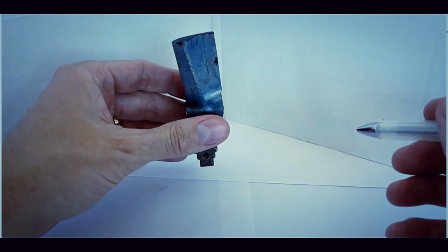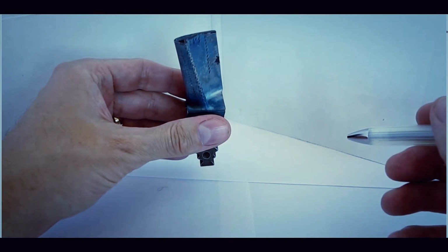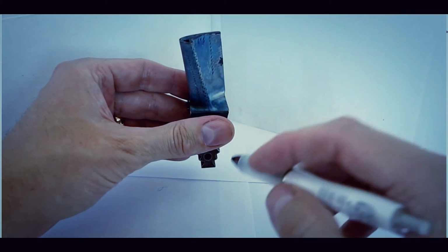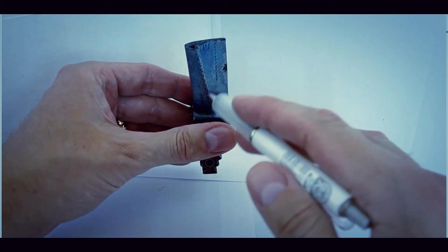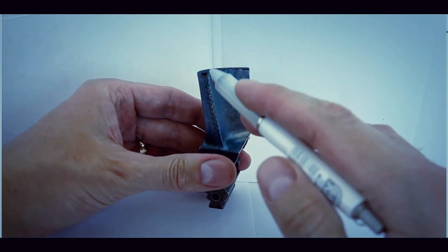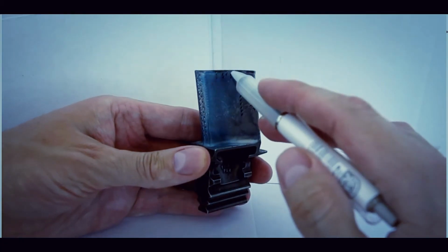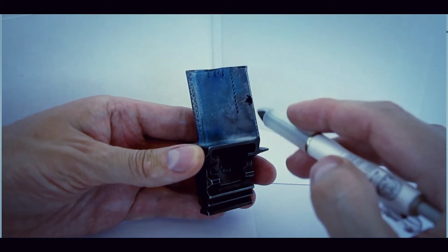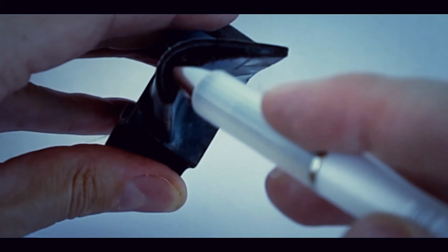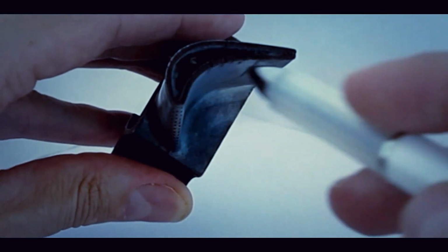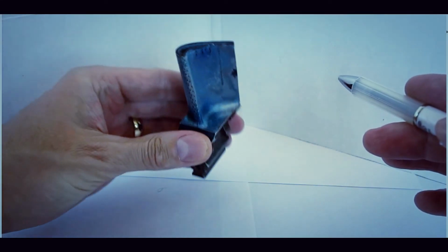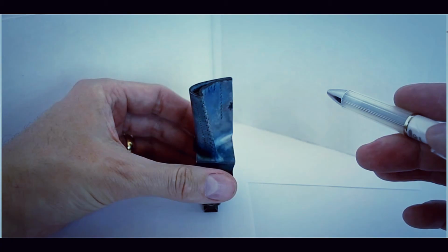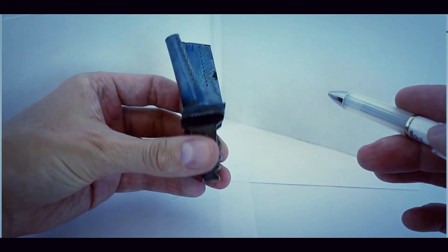And the other thing to notice is that there are a number of ports on the bottom of the blade where it would go in to the engine itself, and compressed air from the compressor would be used and ported through that ducting system, and then it would come out through these small ports. There's some on the leading edge, there's some up on the tip of the blade, some towards the trailing edge, and then even on the tip you can see there are more ports there. Those are used for cooling the blade due to the hot combustion gases, and that is the gas turbine blade.